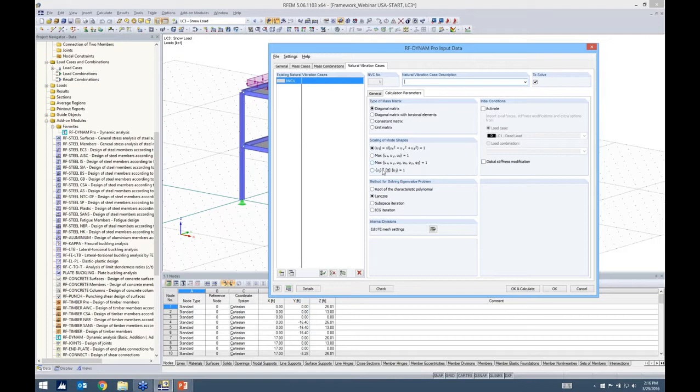This other option here is actually used internally for a response spectrum analysis and time history despite our selection of these 3. So keep in mind that this is used internally anyway. This is where modal masses are set to 1 pound for each eigenvalue.